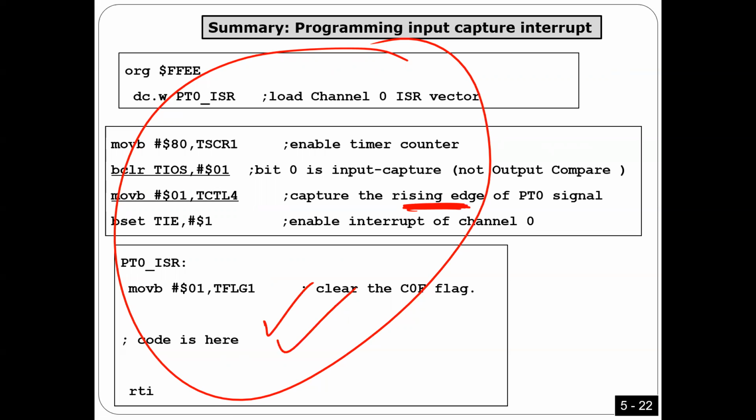Usually, if you want to measure time, I have to write a command here to store TC somewhere, because I want to clear it for the second value. But in case of IRQ, I don't care about TC. I don't care about the time. All I need is that every time there is a rising edge, there is an interrupt like IRQ.